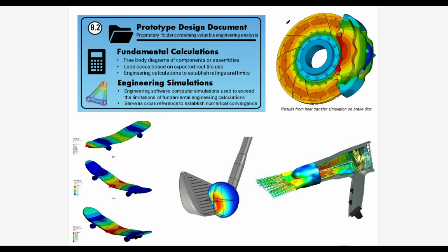Now, in this case, we want to know how big is the vehicle, how much does it weigh, and how fast is it going to go. And based off of that input, you can create a simulation that can properly recreate how much heat is created in these brakes, and that will ultimately guide you in the material choice that you need to create for this brake system, right? So the fundamental calculations of physics will lead you to inputs for your system.